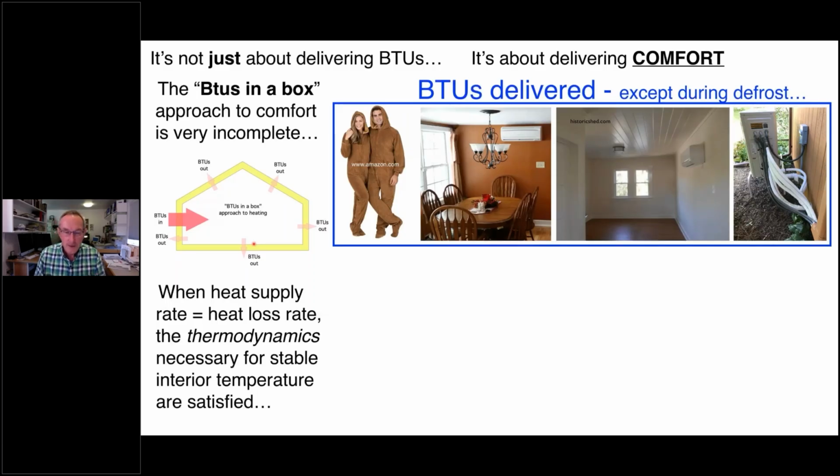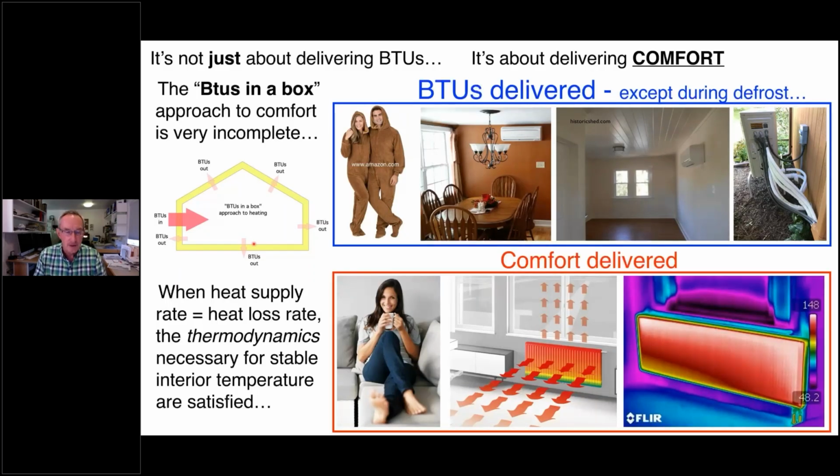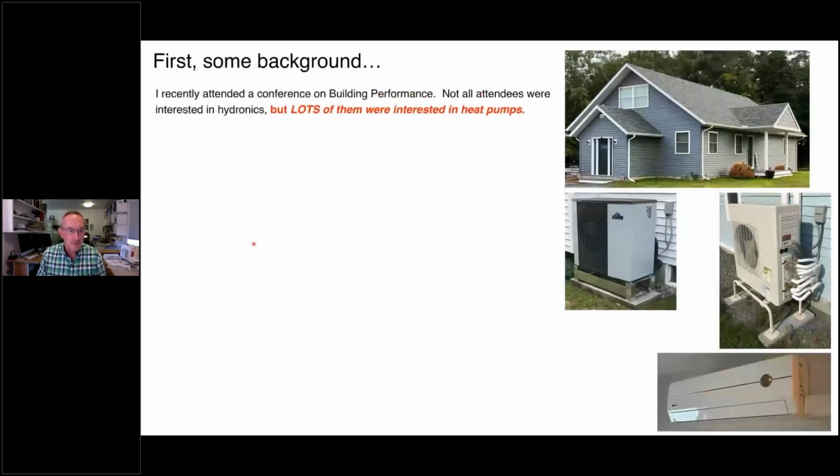With properly designed hydronic delivery systems that look at both air temperature as well as surface temperatures, it could be radiant panel heating from the floor, wall, or ceiling, or it could be panel radiators. But the bottom line is we can better supply human physiological comfort using hydronic-based systems compared to all air systems. Okay.